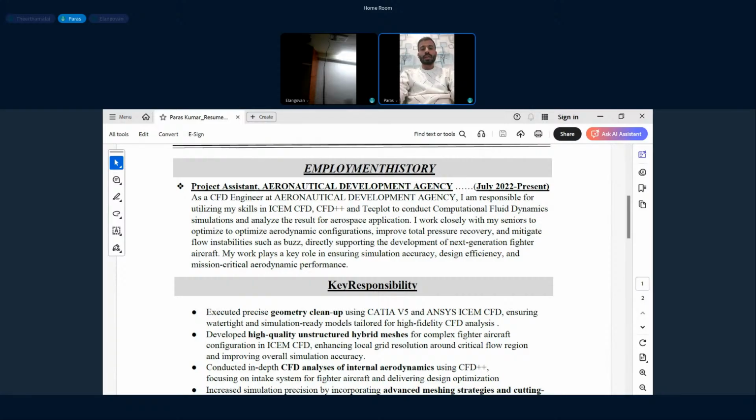There are many other models also, like K omega and K epsilon. K omega is especially accurate for the wall boundaries, but is not accurate for the free stream when we go above the free streams. But K epsilon is accurate on the free stream, but not accurate to the wall boundaries. So we are using K omega SST, which is the blended function of the K epsilon and the K omega. So it will give the accurate result at the boundaries also and free stream also.